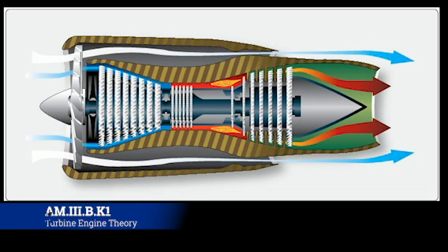or you'll hear people refer to it as the hot section, because that's where the actual fire happens. In there, you're going to have igniters with fuel spray nozzles next to them. So that super compressed air is going to get sprayed with fuel to give you that 1-to-1 ratio. Then there's an igniter right there that's going to spark it, and when it sparks, it's going to explode. And when I say explode, I mean it literally explodes. It creates a ball of fire.